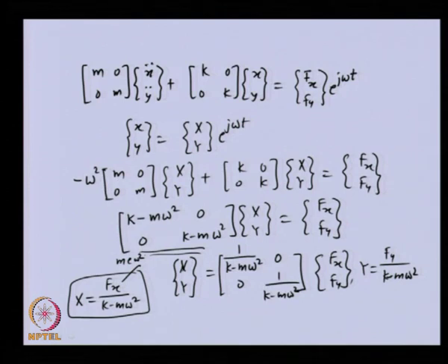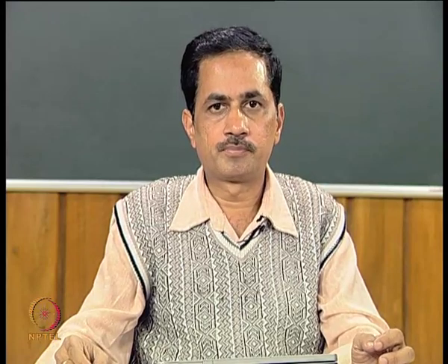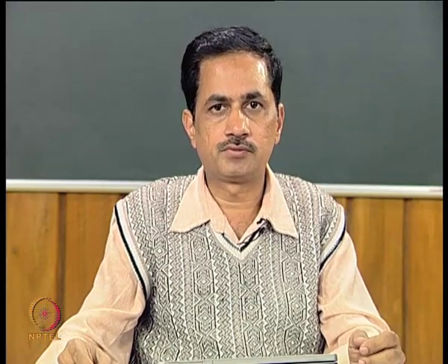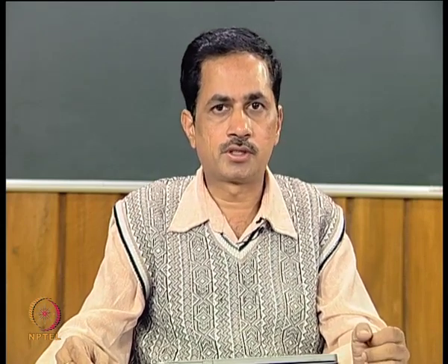So you can see how the matrix method works very conveniently. Only thing is, when damping is there, these matrices will be complex and need to be inverted in complex form. So we have seen the simple Jeffcott rotor model. There is a 2 degree of freedom model in which we neglected the torsional and the transverse vibration coupling.